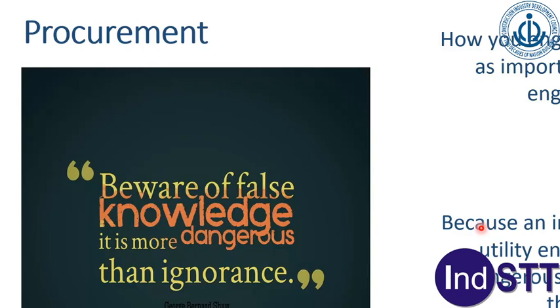So the SUE service provider should be responsible for the accuracy and reliability of the data delivered. Accountability is the key. Written quality assurance procedures are needed, and it's an interpretive science, so experience is critical. Equipment inventory is very important because no single equipment can provide all the information. So you need to have GPR, acoustic locators, induction locators, etc. There should be internal CAD capabilities and, of course, timely performance.